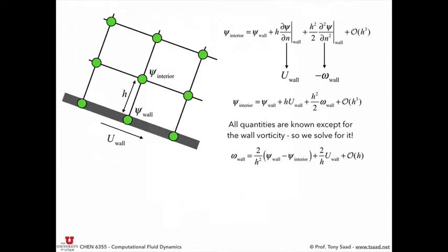So I'm going to take a general discretization for a non-arbitrarily aligned wall. Assume this is a wall, and assume you have a wall velocity. This could be 0, like the left, right, and bottom walls. If it's not 0, then it would be the top boundary.